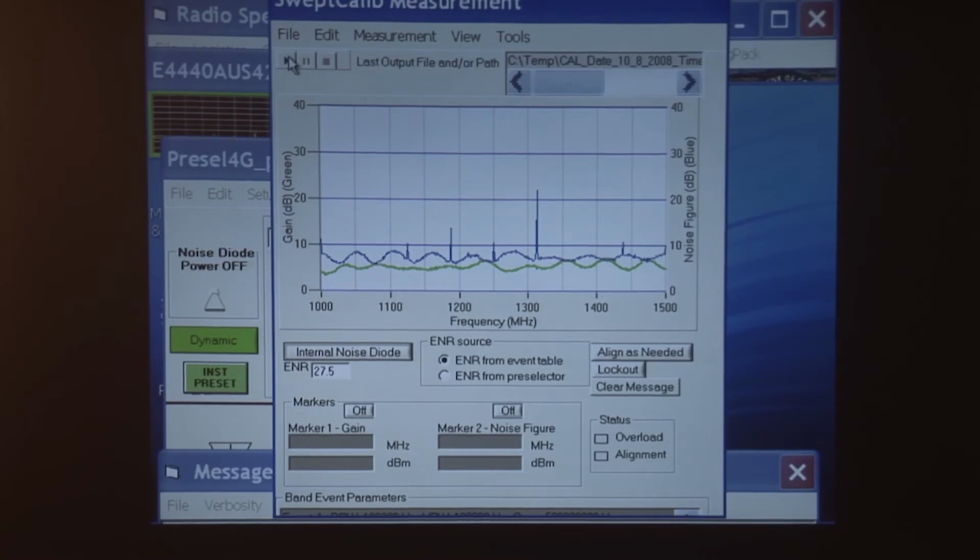This amplifier doesn't have a particularly low noise figure, nor does it have a particularly high gain value, and putting this particular low noise amplifier into the system has actually degraded our performance in terms of sensitivity. So in placing the amplifier where you did, you brought up the signal and the noise together. Yeah, the statement is putting the amplifier where I did brought up the signal and noise together. So we can't see any weaker signal than we could before. We haven't benefited ourselves in any way.